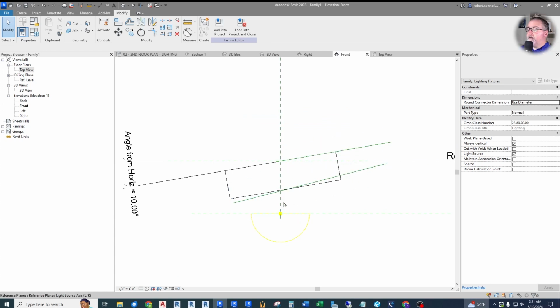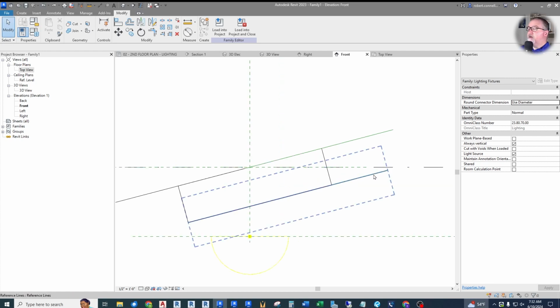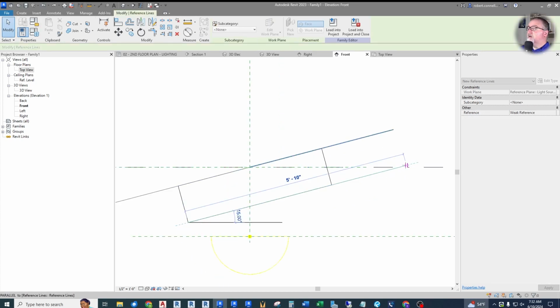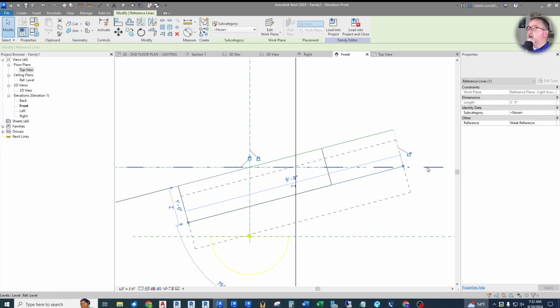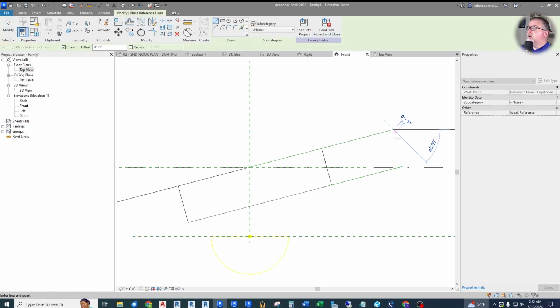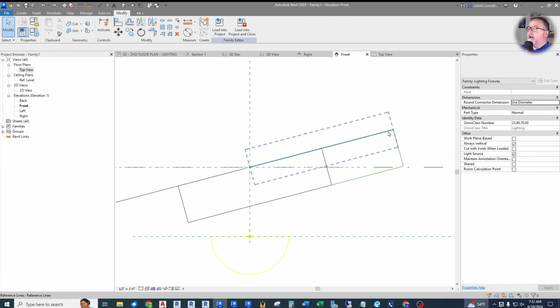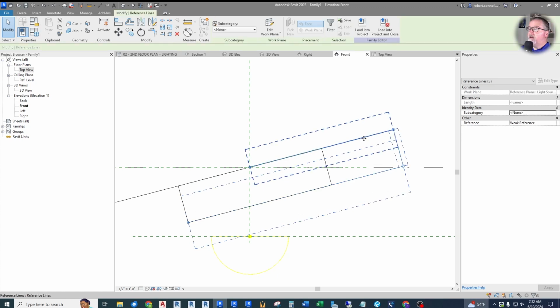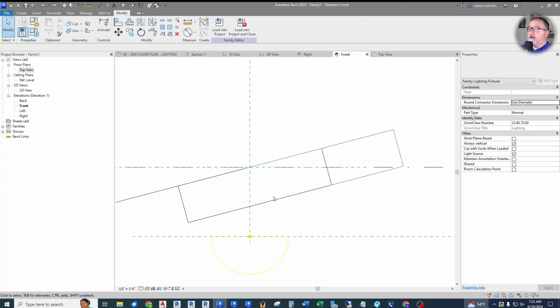So how are we going to tie that one into that? Do we apply the angle to it again? Well, we really want it to move everywhere. So one way to do this is a property of lines is interesting in that if we tie these together, create reference line, we get these tied together. Now they become one piece. If you tab it, you'll see that it actually highlights all of them. So it becomes a chain of lines. Remember how lines chain? Well, that means that they maintain their angular connection.